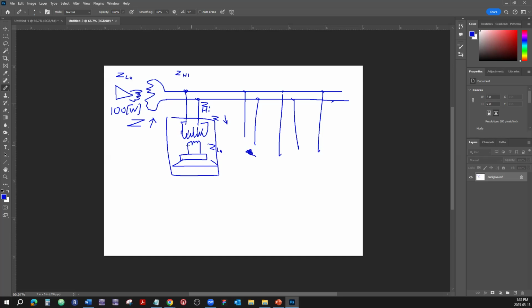There's going to be, at the secondary winding of the transformer, one permanent connection to the 8 ohms. So that's not touched. But the primary winding of the transformer is going to have different wires sticking out of there, tapped at different points when it was wound in the manufacture. And they're going to be labeled quarter watt, half watt, 1 watt, 1.5 watt, maybe 2 watts, 4 watts, something like that.